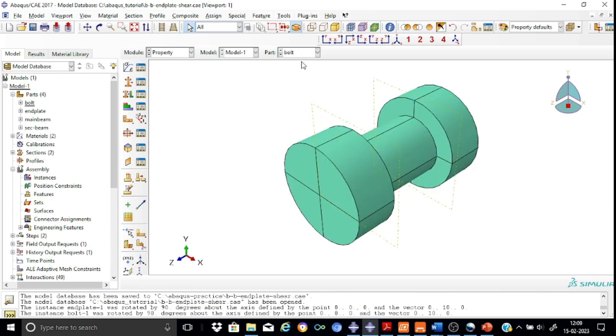Now we also have the model for our bolt. Ensure that here again a proper partitioning is required. As you can see, we have done partitioning at four locations, along the vertical as well as the horizontal diameter, and we also created a partition at the intersection of the shank with the head. That is all regarding the various parts. Please remember that a detailed explanation of how these parts are developed is not attempted here, because that will take away a lot of our time during the presentation.